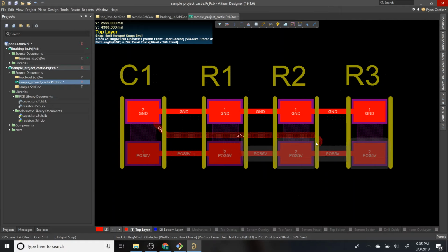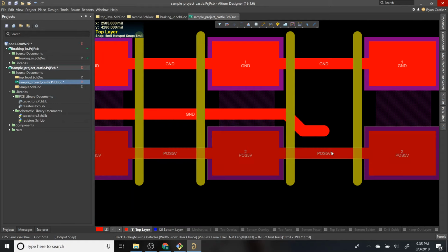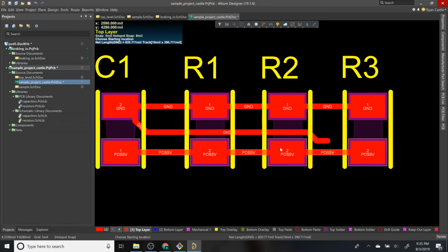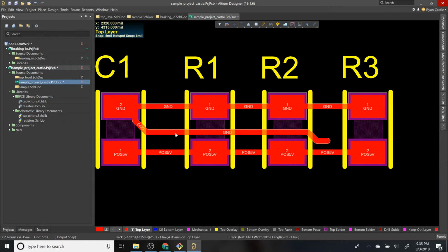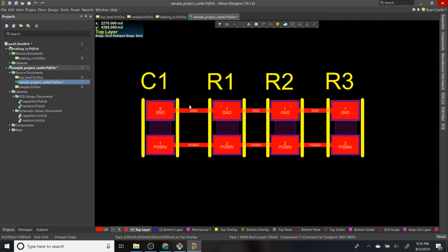Like, I can't get any closer to this net without it causing an issue, so I'm not going to. If you overlapped 5 volts and ground, then you'd short circuit. You wouldn't really want to do anything like that, because that would be bad. There are a ton of design rules, and a ton of different things that you can do.